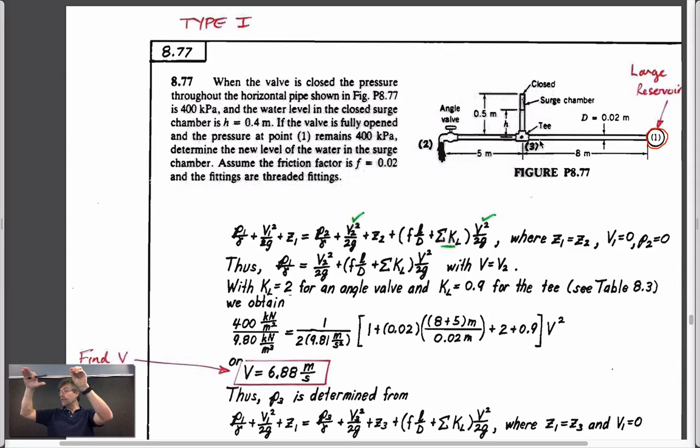Clearly it won't go higher than the water level, because that's, even with inviscid flow, that would be the maximum height, as we know from our other calculations. And so having a surge chamber is not an unusual thing in bigger plants. I don't know whether it's a big thing in this kind of construction. So I digress. So what's the question?